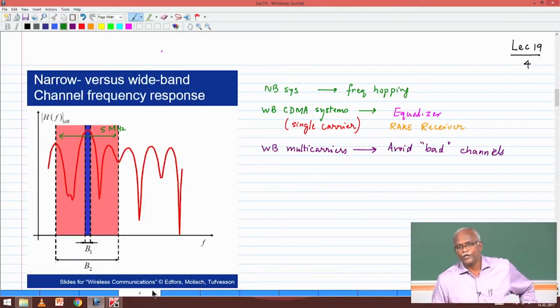To help us put this framework together, we looked at a channel. There is no difference in terms of the channel. If you do a wideband characterization, you will resolve all the multipath. It has a frequency response. But if you were to transmit a GSM signal through this multipath channel at a particular center frequency, we said that it does not see much frequency variation, because it is not resolving the multipath. On the other hand, a wideband CDMA system at 5 megahertz will be able to resolve the multipath, and of course we extended it to the OFDM system as well.